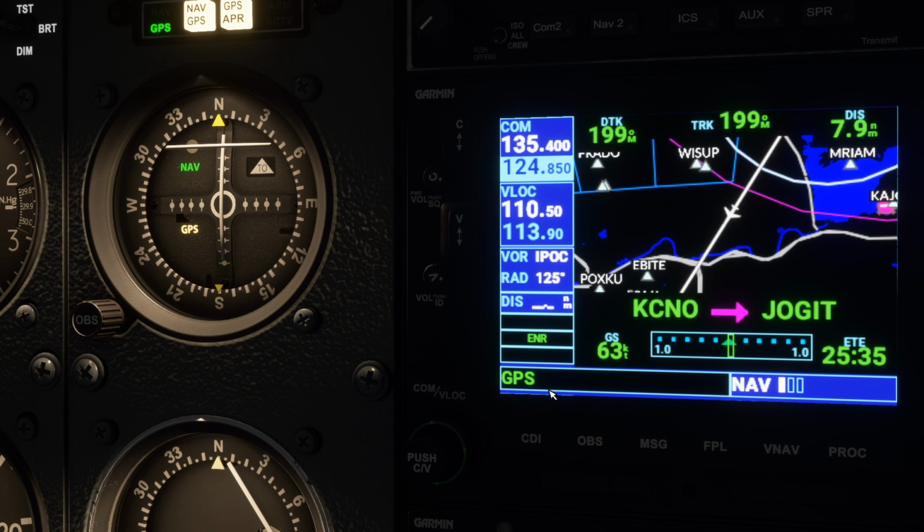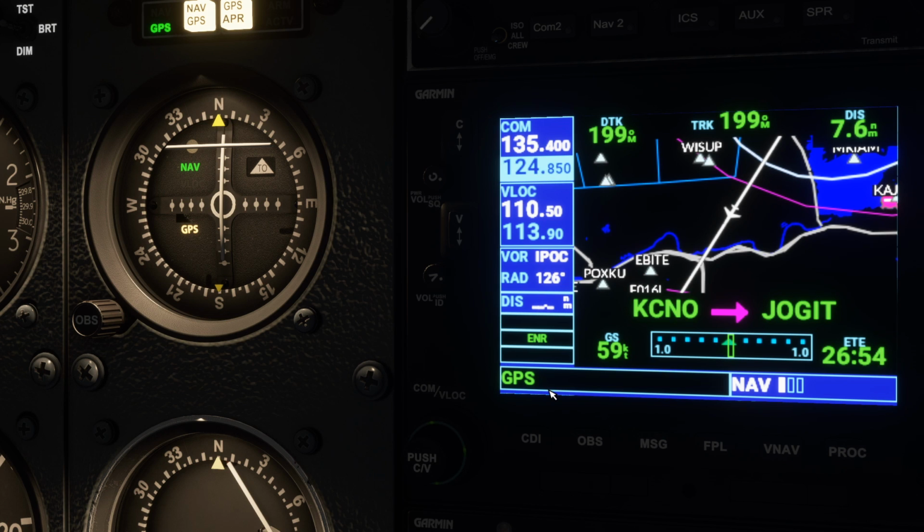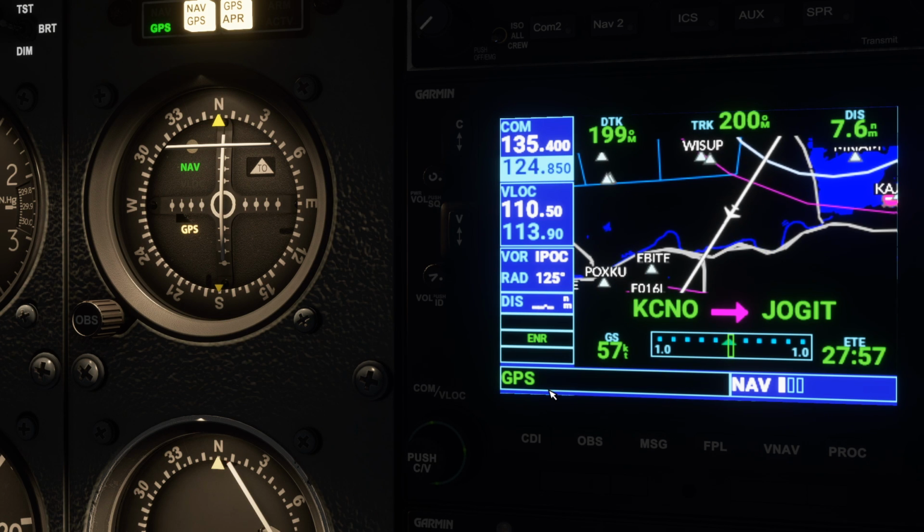And then if we keep following those waypoints, it'll actually still line us up with that runway. But we're not going to use a GPS approach. We're going to be using the ILS approach, which is radio based. And when we use the ILS approach, we not only get the horizontal guidance to line us up with the runway, but we will also get vertical guidance. And we'll use the autopilot to do both of those for us and take us down on our precision approach right down to the runway.